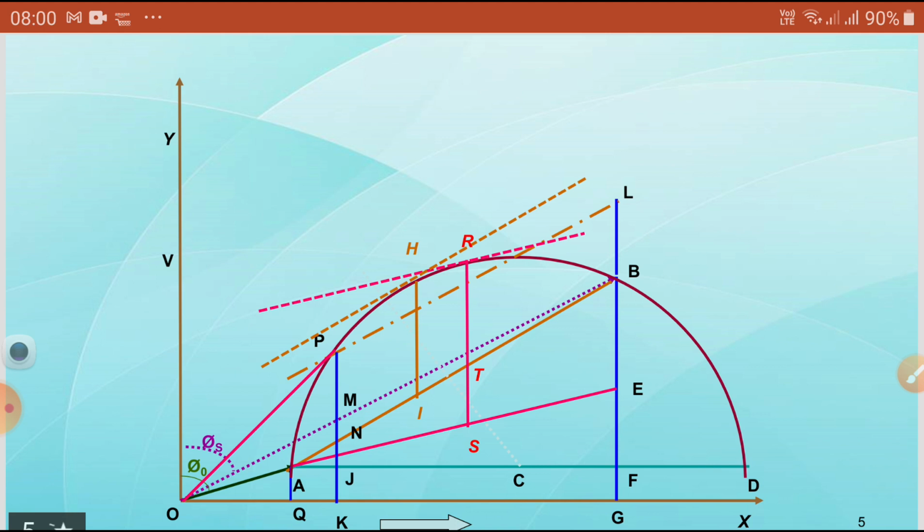Okay. So, what is the formula? Torque is directly proportional to s E2 squared R2 divided by the square root of R2 squared plus (s X2) squared. Okay. Instead of using these mathematical equations to know the starting torque, efficiency, slip, power factor, maximum torque, etc., no need to remember all these laws.